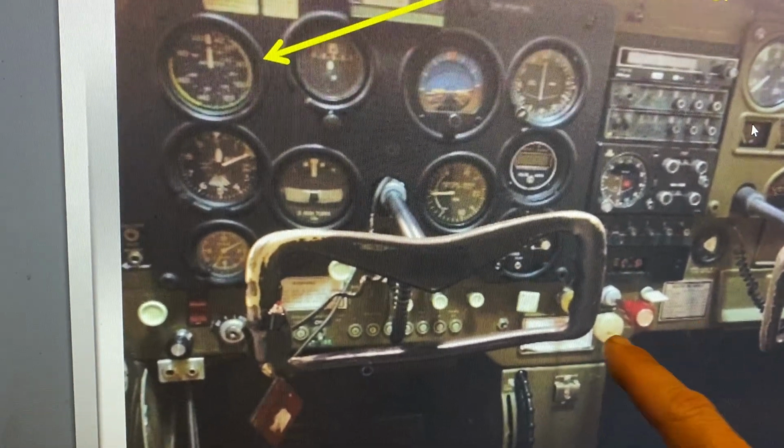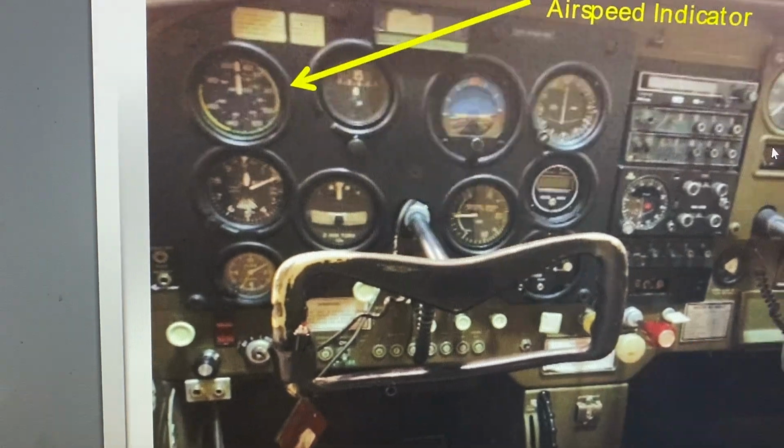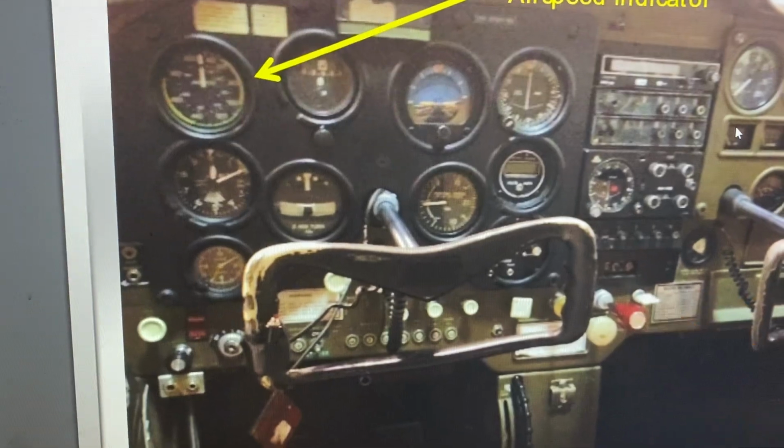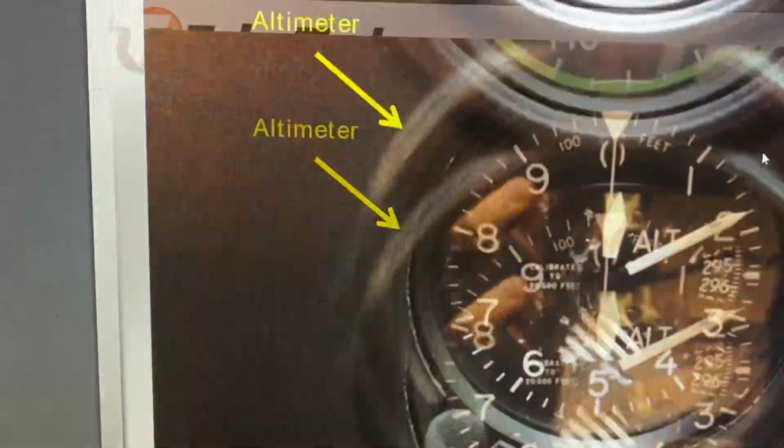Then you're going to set your throttle. So the throttle on this one, you want it to be slightly in. They say cracked or 1/8 of an inch. Let me zoom in on the throttle over here so I can show you what this looks like. A closer picture of the throttle. I know it's coming up here.